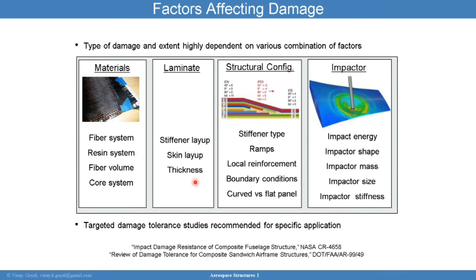When it comes to composites, sometimes when you design them, you put in something called sacrificial layers, so that if the layers on the outside get damaged, you don't take a penalty hit. You don't have to even repair in some cases, although you should for cosmetic reasons, and also you don't want initiation of flaws in those areas. So sometimes repairs are done by cutting out those areas and performing a repair.